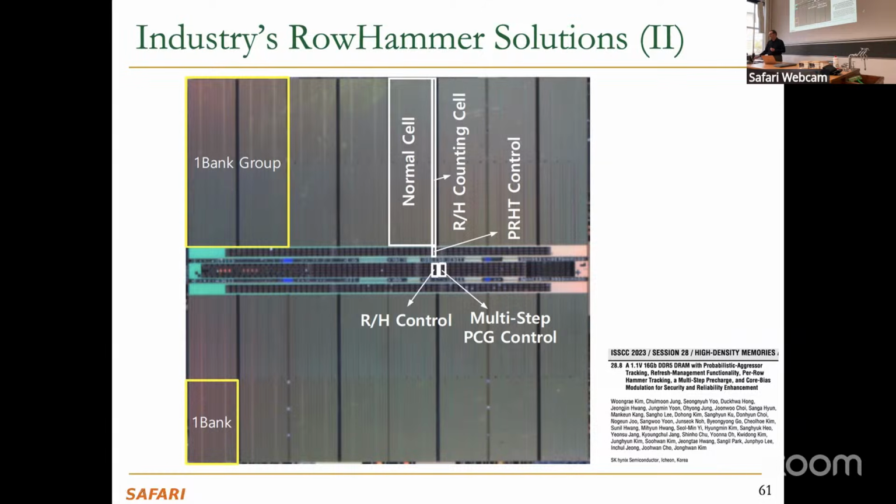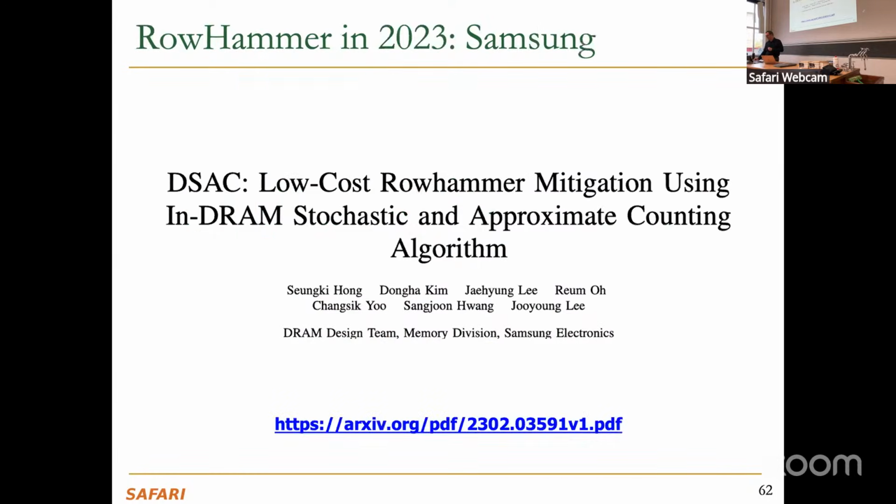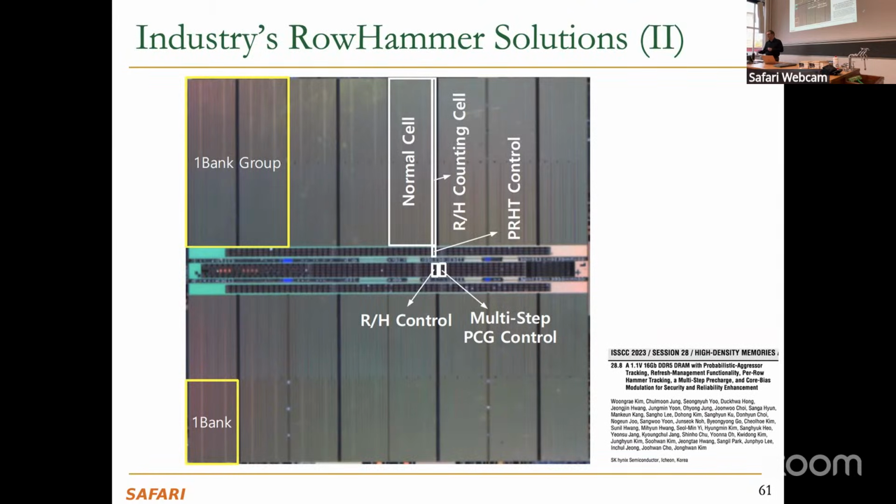The difficulty is now you have more overhead inside the DRAM chip. So every row has some metadata, some other DRAM cells that keep track of the activations, right? How many activations happen in that row. And there's some logic internally to figure out when you should take action. And they don't discuss all of these details, of course. It's still security by obscurity. But the good news is there's something being done. So that's one approach. This is one that's standardized.